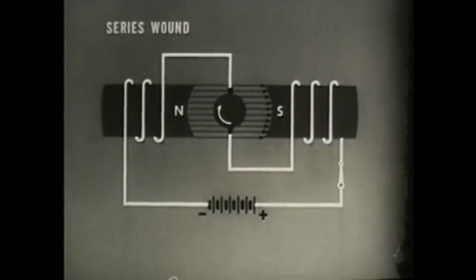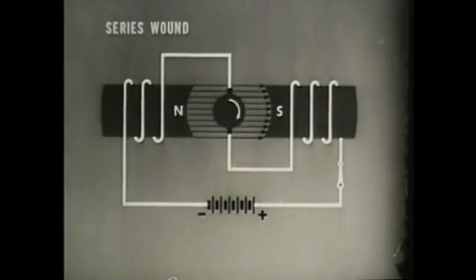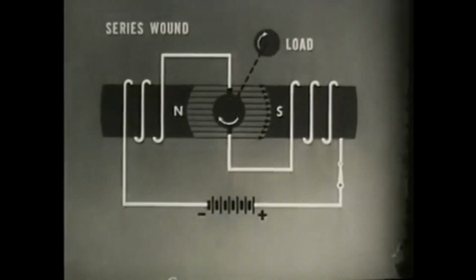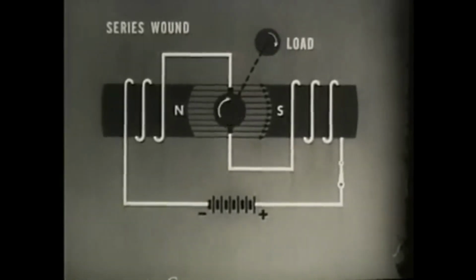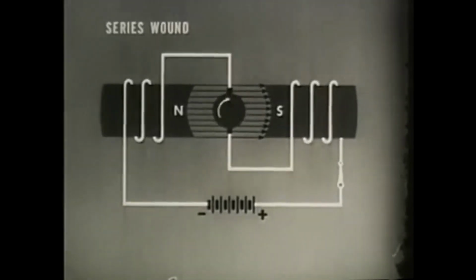The motor begins to turn, attempting to develop enough CEMF to completely oppose the applied EMF. The load prevents this, acting to control the speed of the motor. But if the load is suddenly removed, like in the case of a broken belt, the motor will build up speed trying to develop more CEMF until it destroys itself.